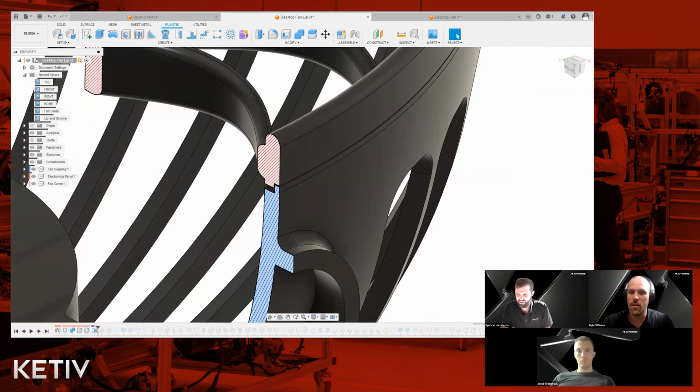And the reason why this is important is, with injection molding, obviously you can have shrinkage defects when things cool. Things can become warped along the seam. And with a zero tolerance face like those were before, that can become quite obvious. So the lip and groove helps to alleviate that issue.